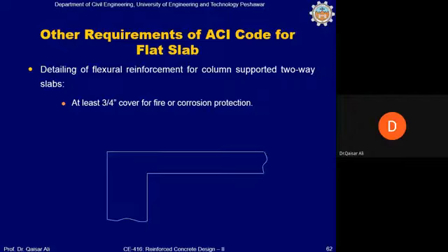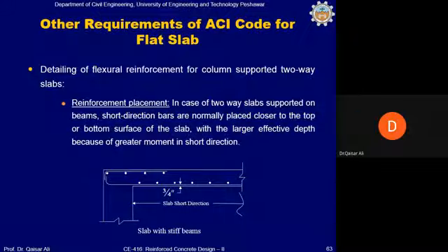Then the 3/4 inch cover, you know this very well, for negative as well as for positive reinforcement shall be maintained everywhere. This is for fire protection and corrosion protection. Okay, reinforcement placement, how the reinforcement shall be placed. This is important to note. You should pay attention to this.